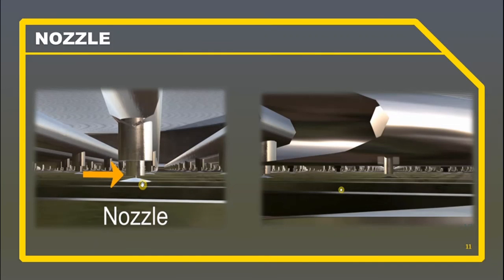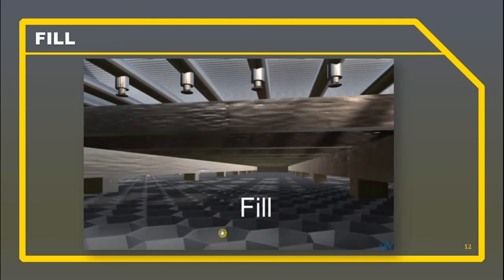Once all the distribution pipes are charged with hot water, it will pass through the second part of the distribution manifold, which is called spray nozzles. The hot water inside the pipe will impact the end of the nozzle, which will create a circular spray pattern. All the nozzles will create this circular pattern, then the water will drip onto the surface of the fill.